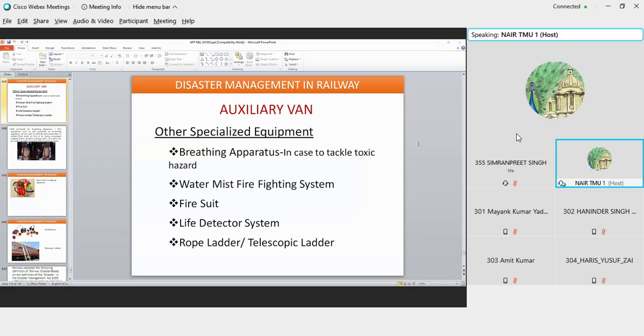So in a scenario, what happens if I'm doing the lifting process and the main power pack fails? I have an auxiliary power pack which cuts in, which will help me to lower the load which is lifted slowly to the ground, and then it'll help me to pack the crane. That means the auxiliary power pack will help me to lower the boom or the jib and pack the crane, and I'll take the crane back and bring in another crane and say that this crane has failed because the power pack has failed.